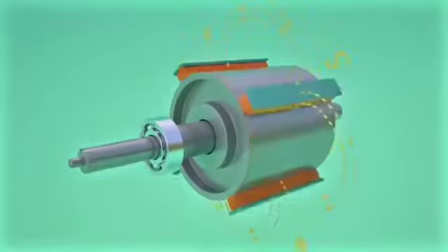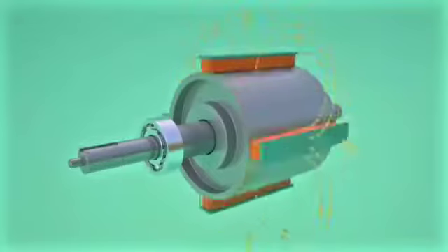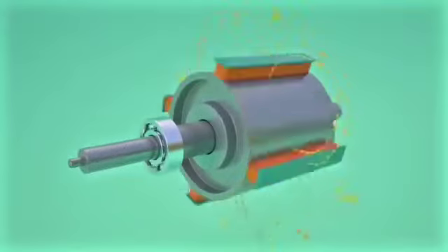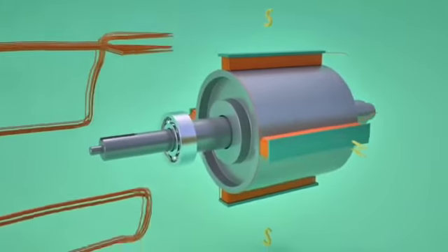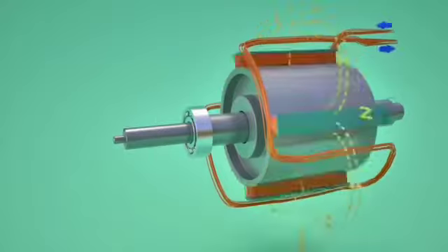Magnetic field produced around it would be as shown. The rotor is made to rotate using the shaft. This makes the rotor flux also rotate along with it, at the same speed. Such revolving magnetic flux now intersects the armature coils, which is fitted around the rotor. This will generate an alternating EMF across the winding.